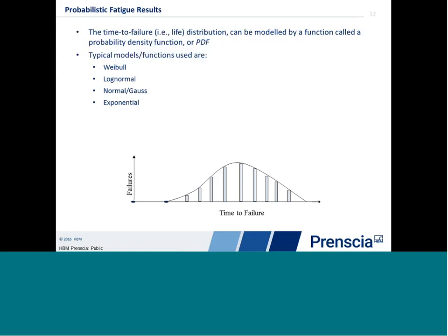The exponential distribution, the last one we see here, is not used much in durability because exponential distributions say that we have a constant failure rate over time. In other words, things just fail on their own without time influencing them in any way. Some people talk about this as car accidents or lightning strikes. If we're designing against randomly occurring events, that might be useful. But in a fatigue and durability sense, we more often use a log normal or a Weibull distribution because both of them show increasing failure probability over time.